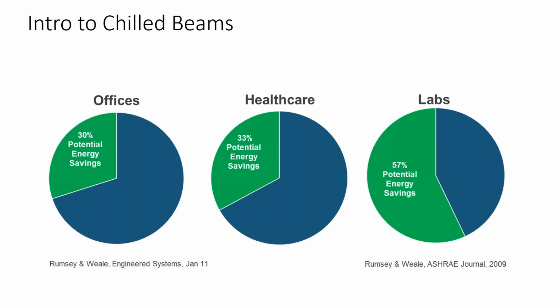Now the real basics of why we have achieved such good energy savings with chilled beams is that we're reducing, again, the ductwork and the amount of air we're using to transfer energy throughout the building, down to basically your latent requirement or your ventilation requirement in the space. So that's going to obviously downsize the horsepower required, the fan energy needed to move that air in the space. And you're shifting that over to pumps and over to the water side.